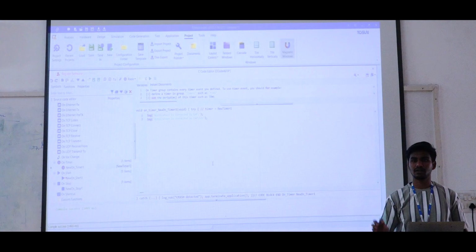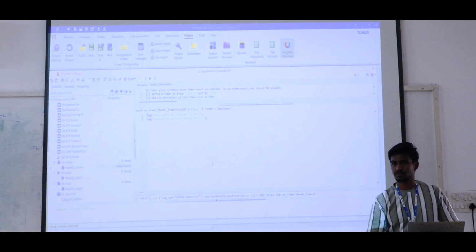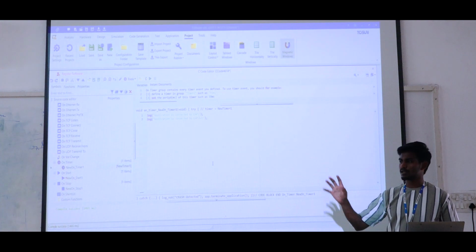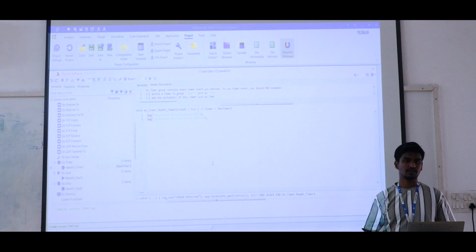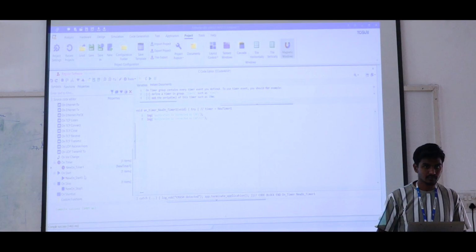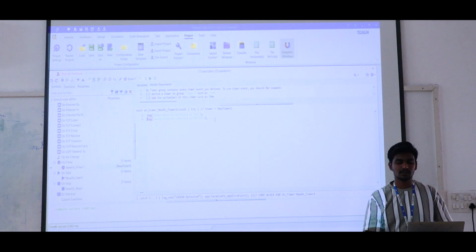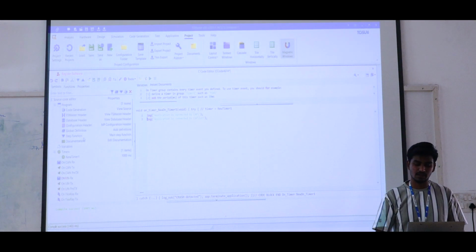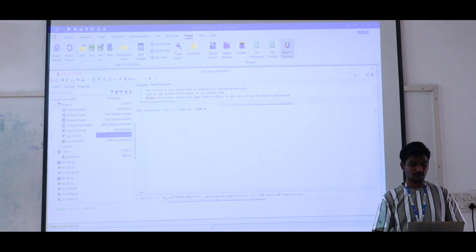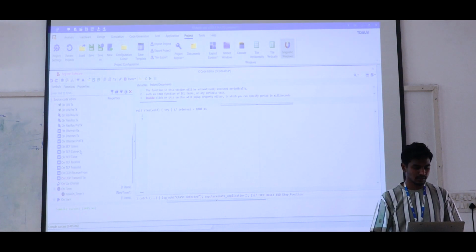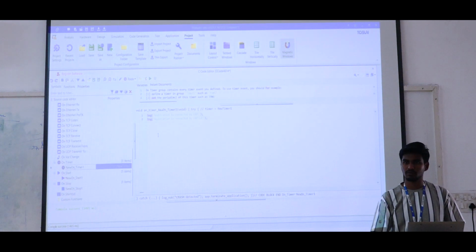Now I just explained it with printf statements only, but we are working with all the CAN messages. I have explained the understanding of the event with these printf statements. On timer you just place the log event. In the step function you just remove it using Control X, or else you get confused, and then paste the same one in new timer.